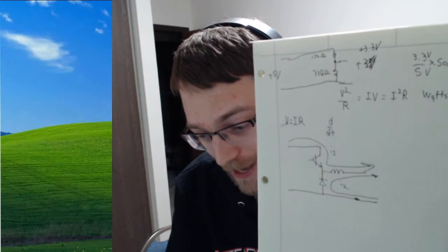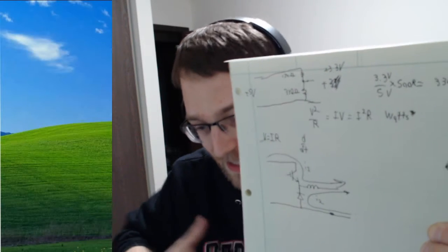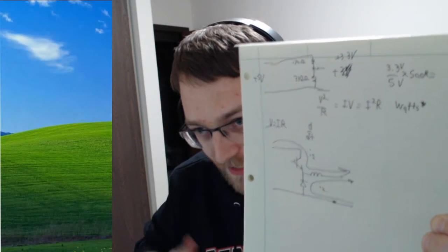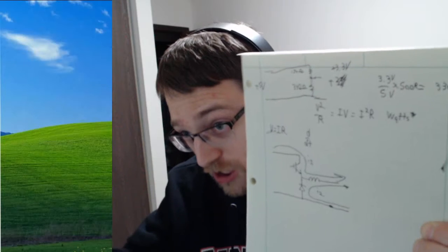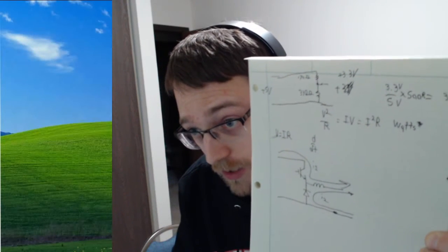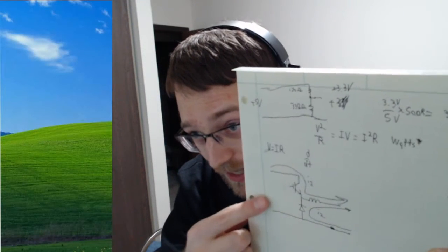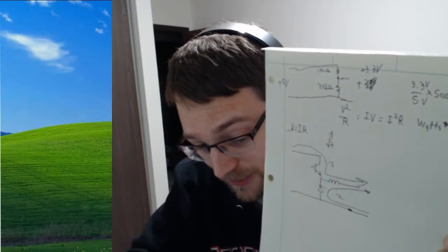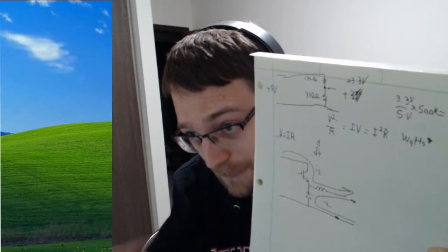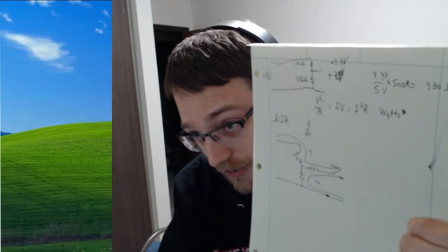So what ends up happening is, when you remove the voltage from the inductor, it has to discharge its magnetic energy, and it discharges magnetic energy by pushing current out into everything else. Current can only flow if it has a return path to go around in a circle. That's what this diode is here for. It's here to close the loop and allow there to be a path for the current to flow so that the voltage can be maintained on the load side.